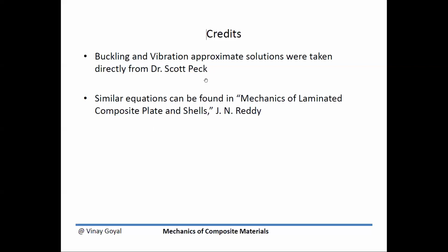We took that to our advantage, and showed you ways that you can approximate the solution of various problems by assuming an approximation for the deflections and then minimizing the total potential energy with respect to the unknown coefficients from the approximations that we made.